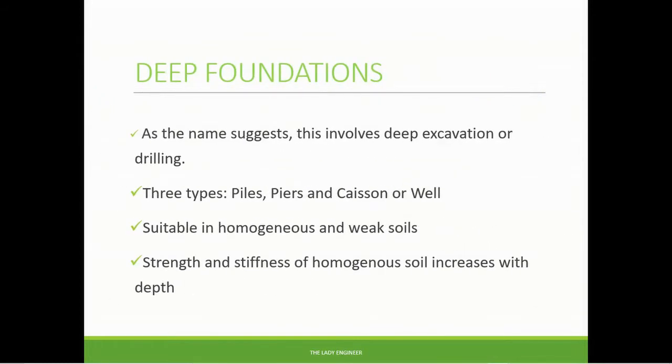Deep foundations. As the name suggests, this involves deep excavations or drilling. We have three main types, namely piles, piers, and caisson or wells. This type of foundation is suitable in homogeneous and weak soils. By homogeneous soil, I mean the type of soil that has the same particle size. When you have the same particle size in soils, it means the air spaces that remain in the soil cannot easily be filled, which renders the soil weak.